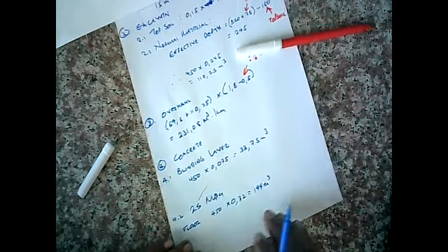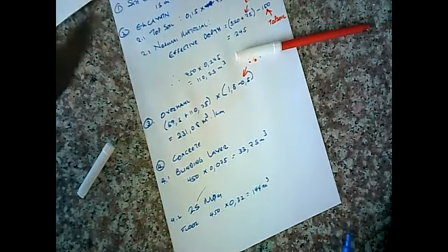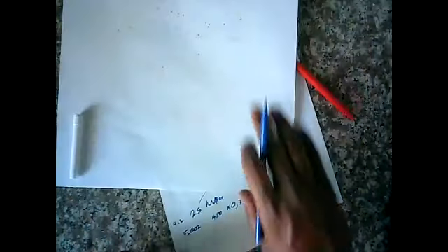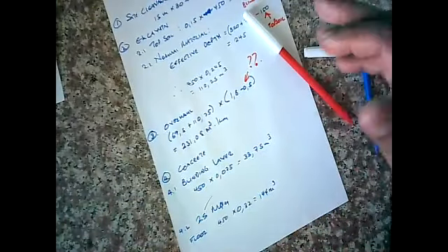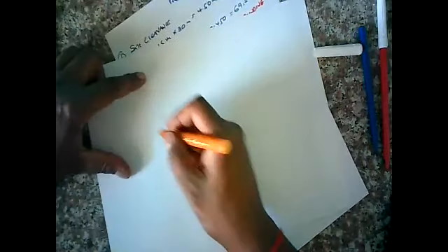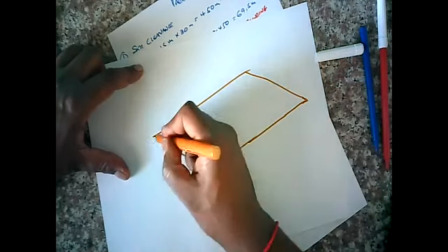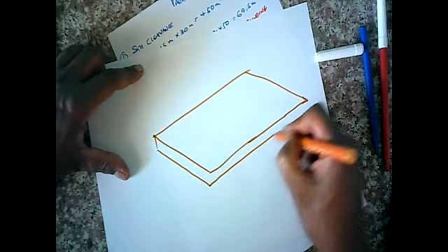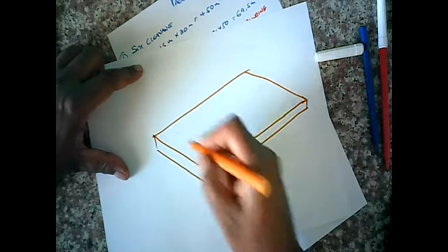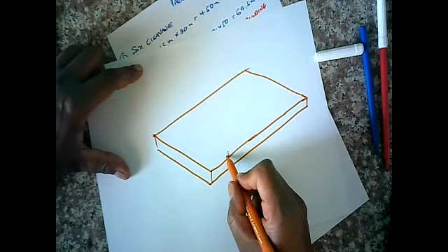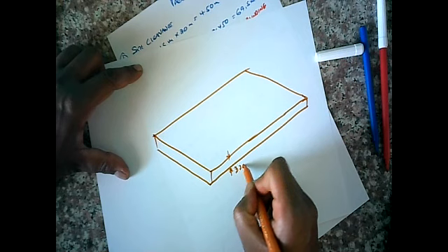All right, so let's look at it in terms of the sketch so that you understand how to break up the structure as you are quantifying. So we put on the floor concrete, and we know the floor thickness is 320. So from there to there is 320.